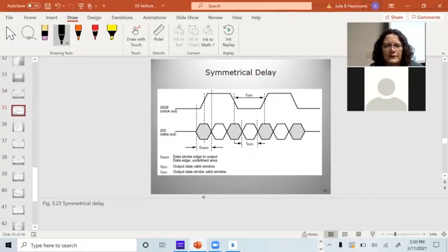This is the idea right here. This is the clock. The clock actually has skew on it. It's not a perfect square wave. It takes time. But when I get that first clock edge, I want to put this data out. And this is DDR2 because it looks like I'm getting 4 data packets out per clock. No signal in there to strobe it.